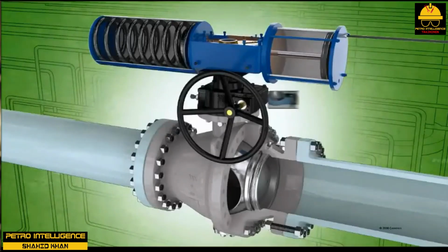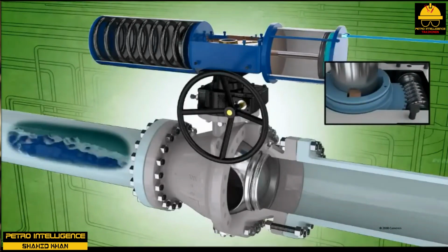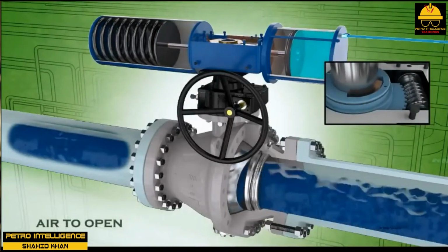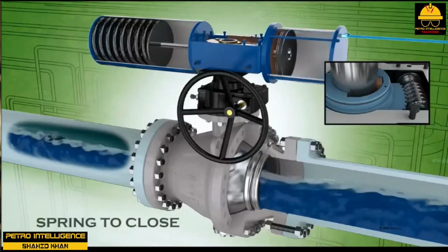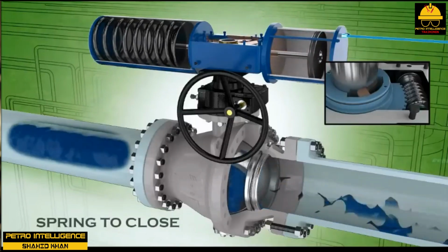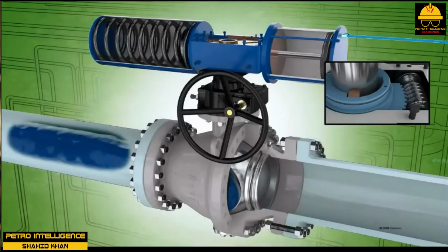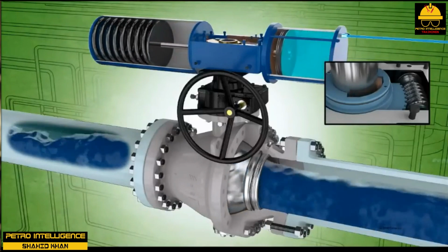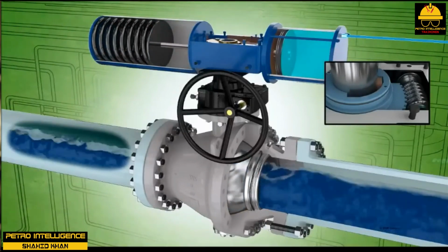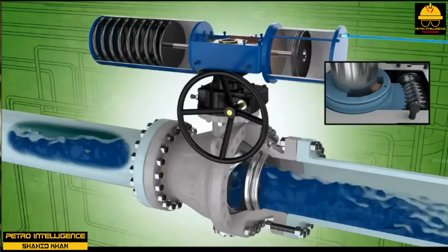Hydraulically operated actuators convert liquid pressure to mechanical energy. The hydraulic actuator uses a liquid-tight cylinder and piston to move or position the stem. It is commonly found in use with automated gate valves or slide valves and is used where a lot of stem travel is needed. The following expressions are used commonly to describe actuators.